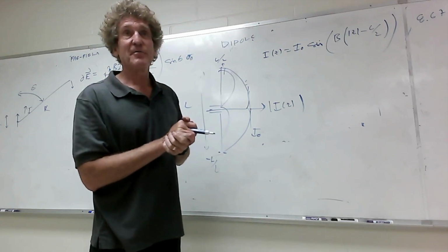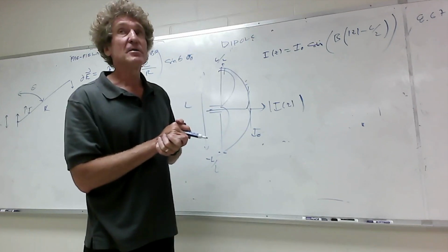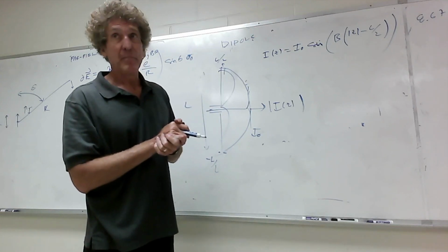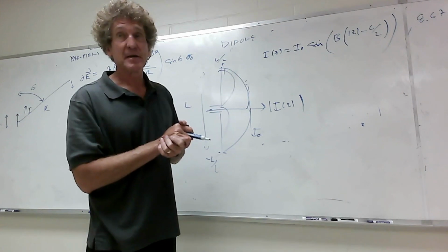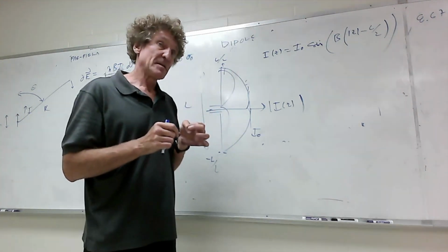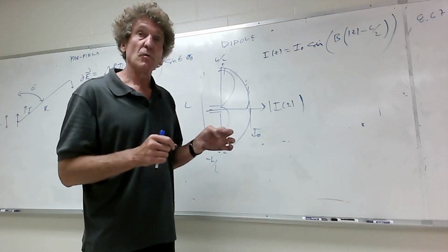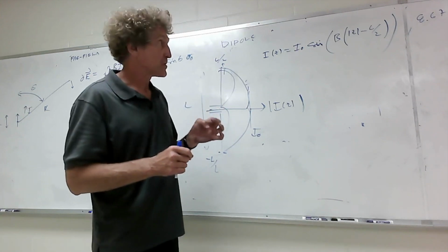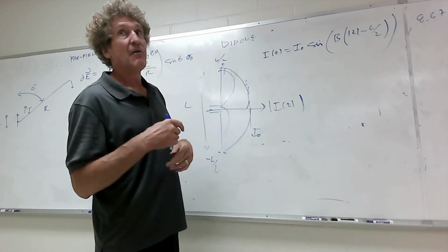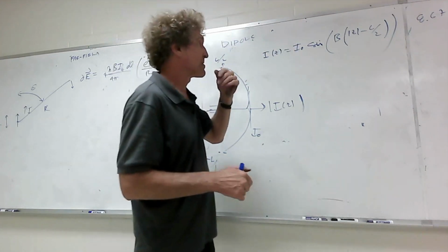Now, the truth is, if you have a real dipole, and it's a half wavelength, you will get a trickle current, but it'll be very low. The reason is that, first of all, it's an approximation, and a lot of this has to do with the thickness of the wire. The larger the wire radius, the more perturbed it is from that exact solution. But just do the math on this stuff.